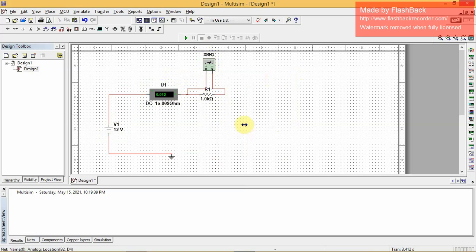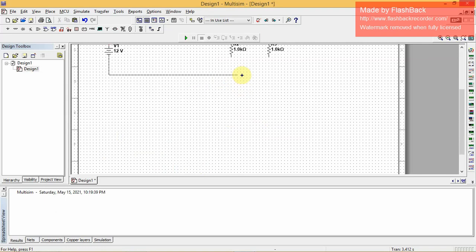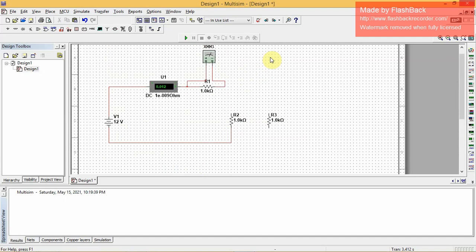If you wanted to add another resistor here, you can copy this one, Control C, Control V to paste, Control R to rotate, and you can copy this one again, Control C, Control V to paste, and there you already have two resistors. Let's drag this down a little. No, let's remove you. Right, connect that over there. I don't know why I dragged this window down. Push that up again, and we'll connect this over there. This goes there, and that goes there.